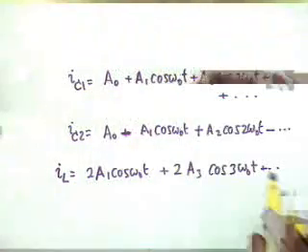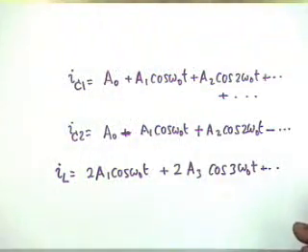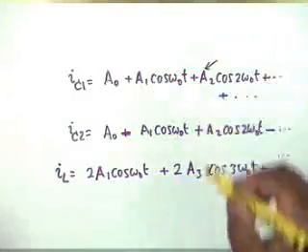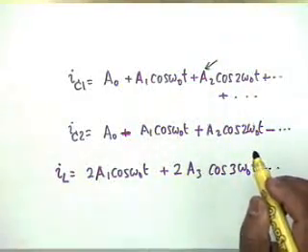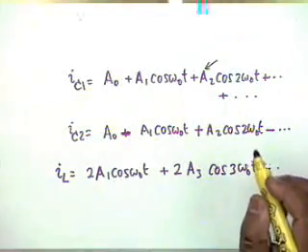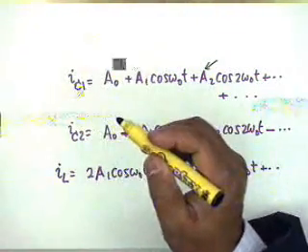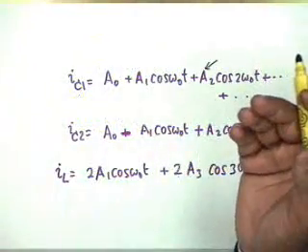As you know from general experience of Fourier series expansion, these amplitudes A0, A1, A2 usually for a half rectified sine wave are in decreasing order of magnitude, and therefore this second harmonic is the major cause of distortion in IC1. The major harmonic component in IC1 is the second harmonic, because the amplitudes are in decreasing order, and the second harmonic gets cancelled out.